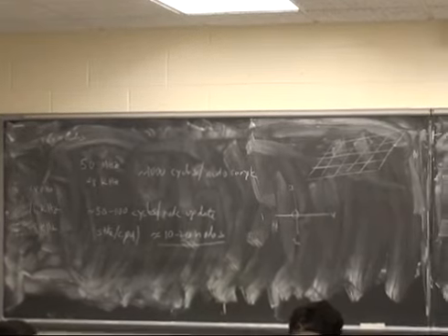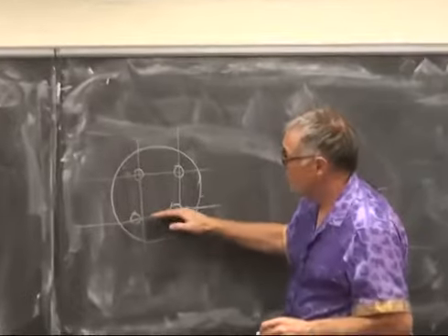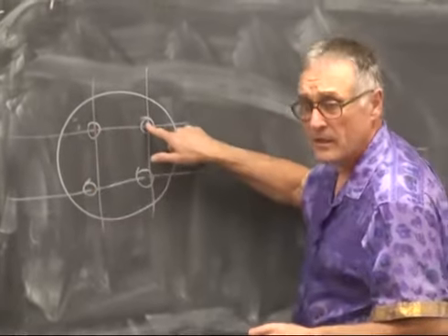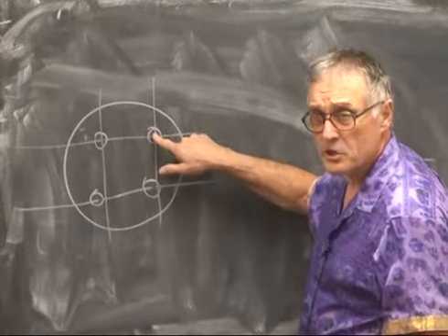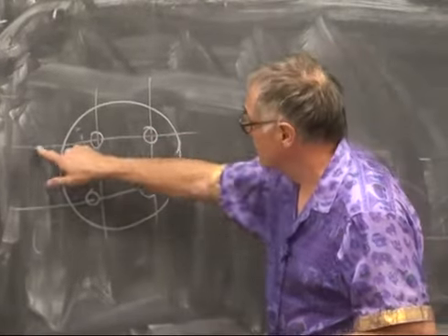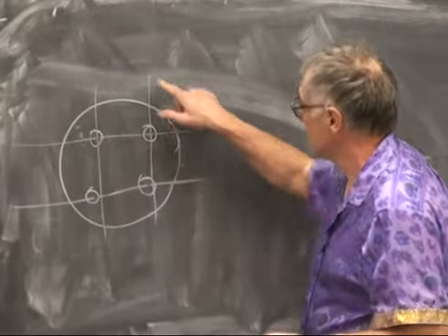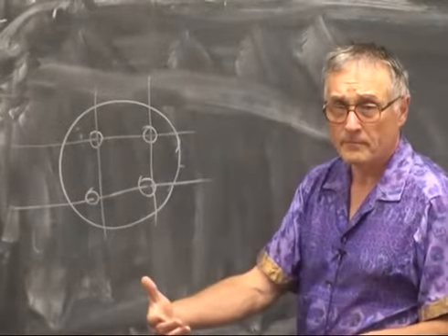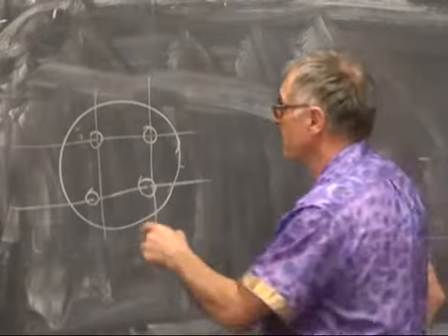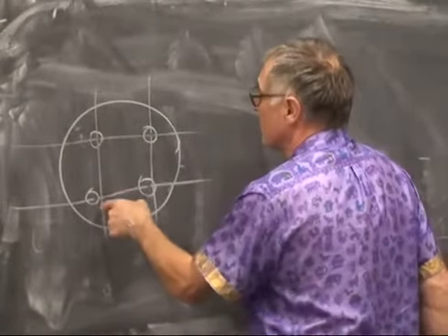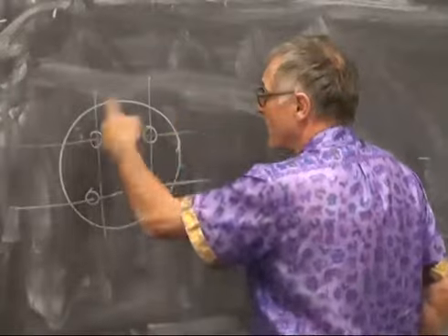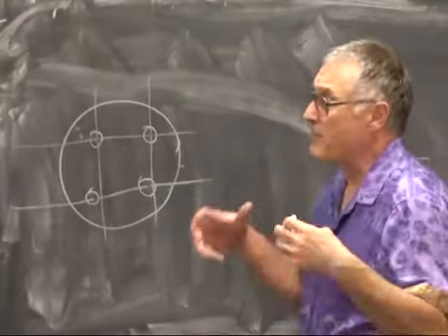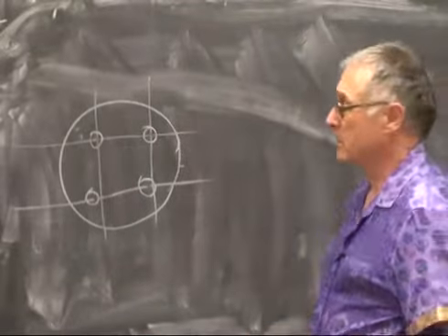So now you're doing 4-way calculation. You would update these sequentially in a sequential machine, and then update the I/O lines sequentially before the next time tick. So here you would have a 4-way serial update followed by an 8-way communication update, and then the next clock cycle would start.